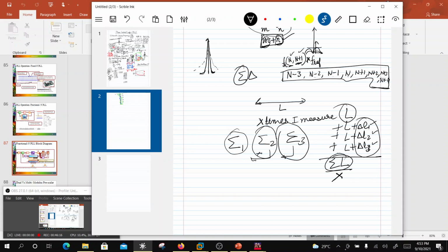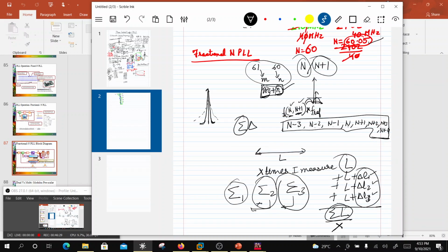If I do a third order, and that is the final order, so basically I am compensating for first and second order, but for the third order I don't have a compensation beyond that. So that is going to be at higher frequency. So what is happening is that the noise is going to be shaped out like this, and it again picks up on both the sides, and this basically is your loop bandwidth.